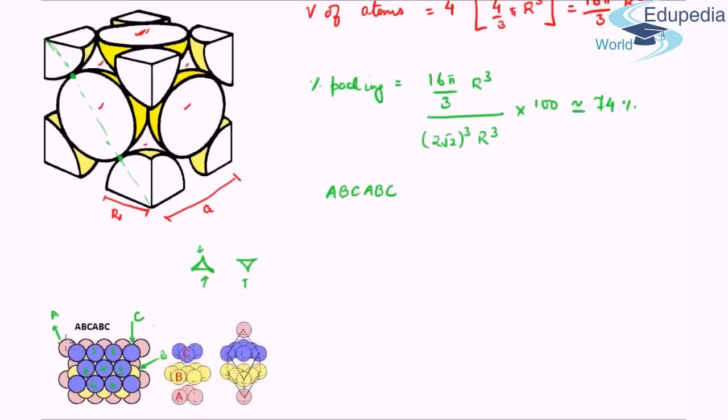If I go again on top of the A layer for the third layer, then what we get is known as AB packing. That is first layer upper triangle hollow, then again first layer upper triangle hollow. But if you lay down the first layer, for the second layer you go for this hollow, and for the third layer you go for the other sided void, then what you get is ABC kind of packing. You have 3 distinct layers.